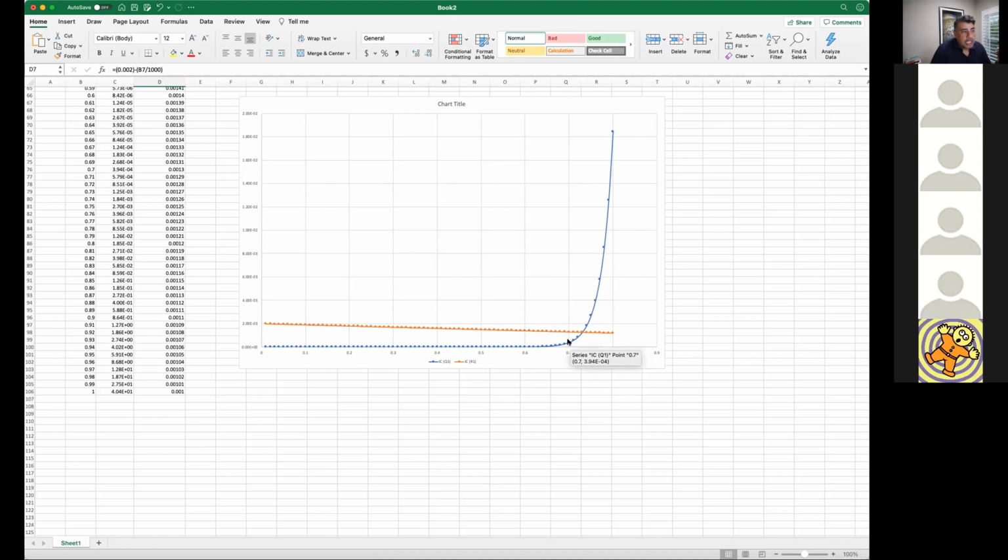So you go, okay, I need to bring up the value for the transistor. Let me pick a higher number than 0.7. Let's say you go nuts and pick 0.75. You go up here, and now you get 2.7 milliamps for the transistor and 1.24 for the resistor. Now I went too high, so let me split the difference, and you come down here.